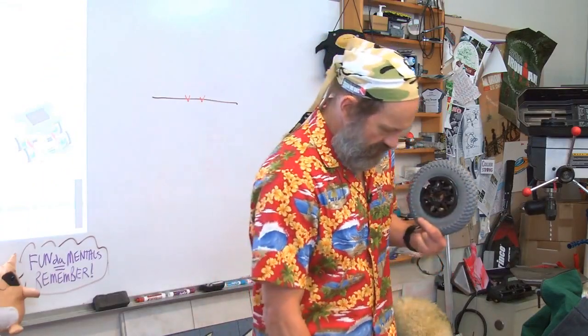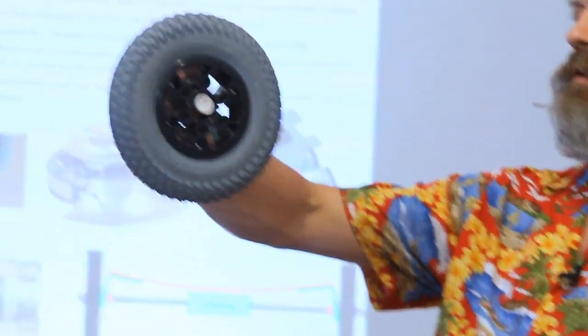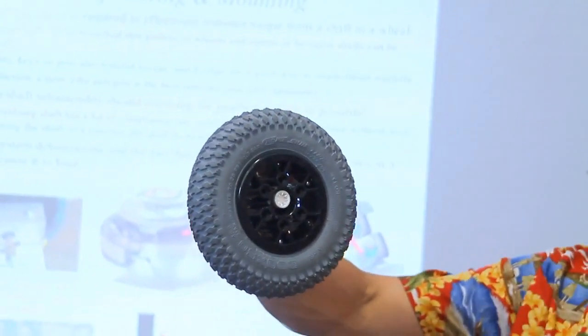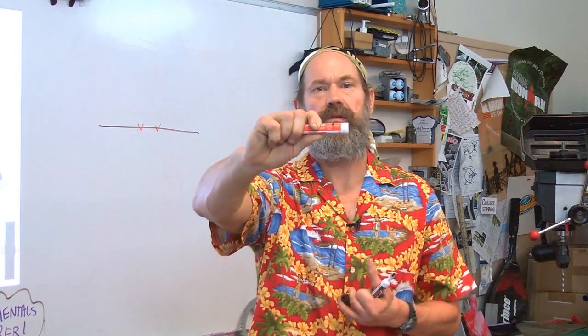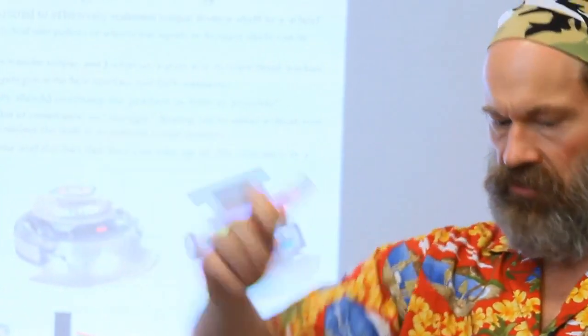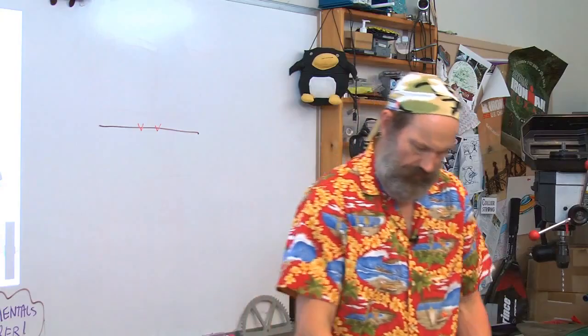And just by its very nature, if you put a shaft through it, and where's the centerline force from the wheel, you're almost by very nature pushing St. Venant to the limit, because here at where this mark is where the center lines of the forces are. That's running about 1.5 diameters. So the shaft is still good if you had a cantilevered shaft with this type of wheel. But you can imagine if the wheel got much thicker, you'd be in trouble.